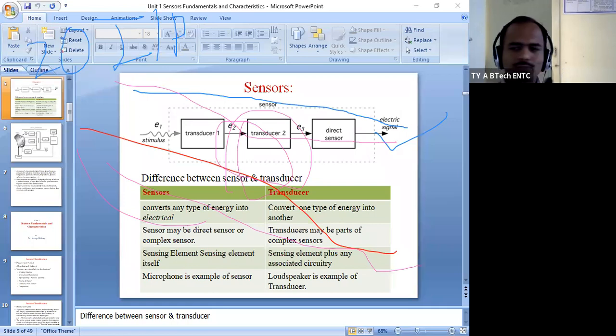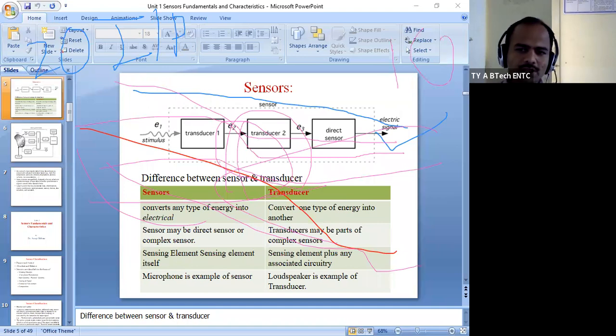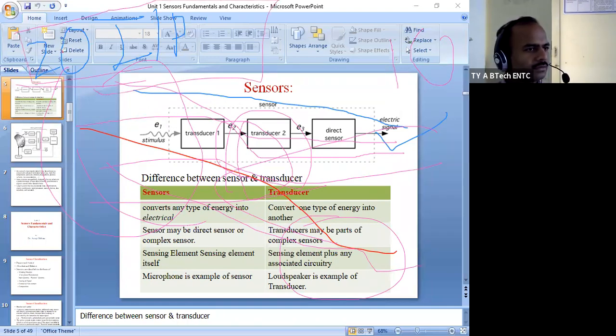It will generate the result with the help of the same A to D and the output will be displayed. After that, the multiplexer selects the second. Again, output will be generated and displayed periodically. Third, fourth, then fifth. So in this way, output will be generated step by step, one by one, and you are able to measure all the input quantities if your controller supports this. Getting? Yes or no? Online guys?